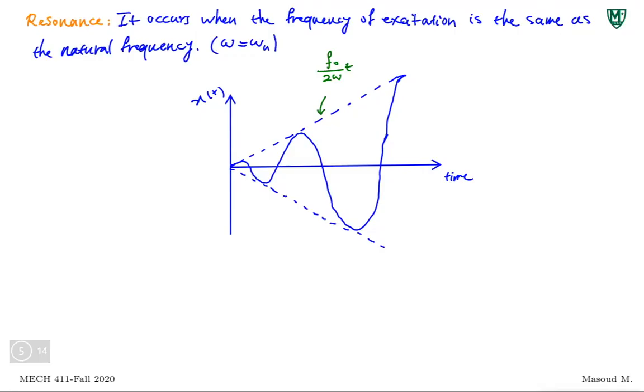In this simple system, there's only one. But when you design shafts, specifically, the first natural frequency is very important, or as we call it, the critical speed, same as natural frequency. Critical speed of a shaft is its natural frequency. So you have to make sure that the operation speed of that shaft is way away from its critical speed.